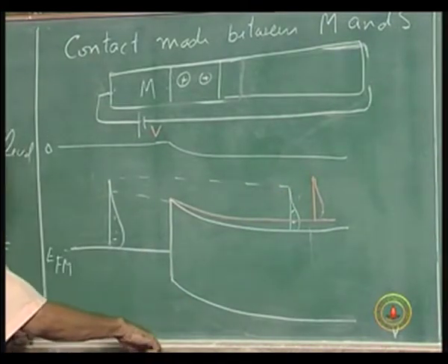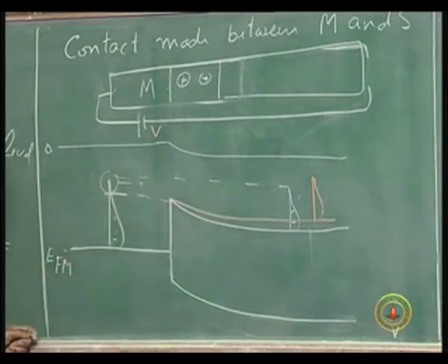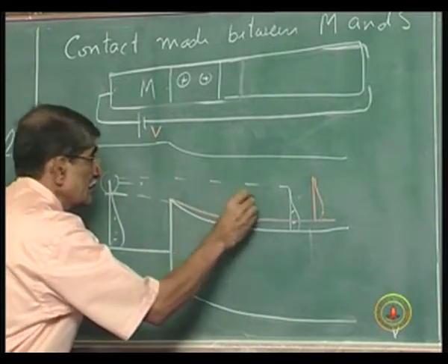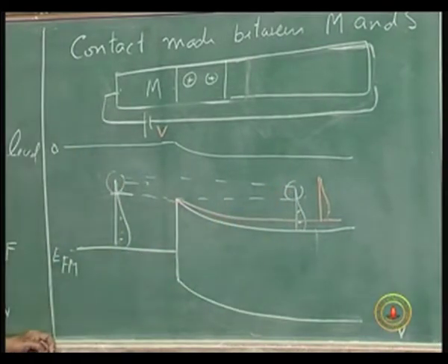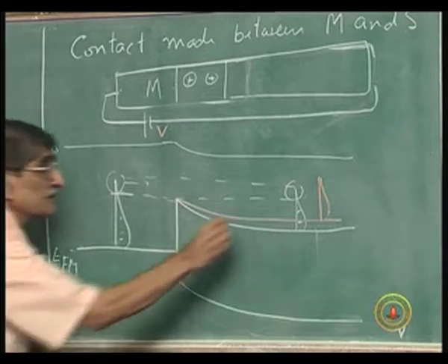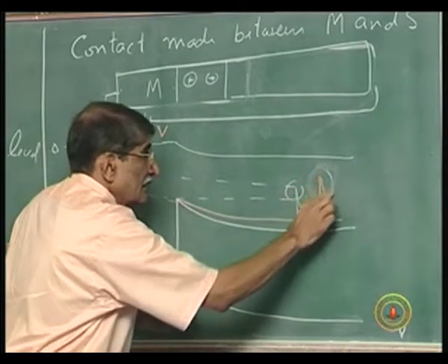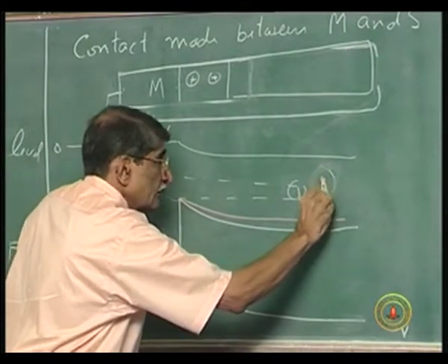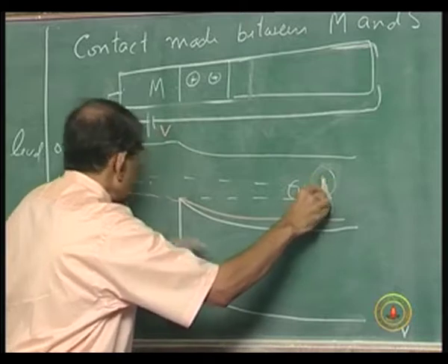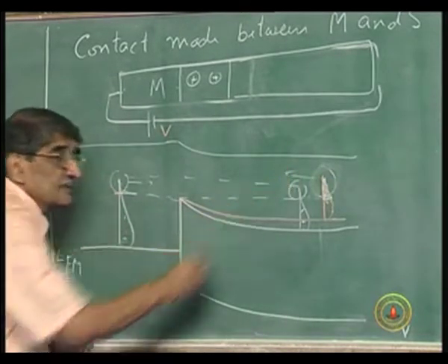Originally you had these electrons which are capable of crossing that side, and correspondingly these electrons which are capable of crossing. Now, you have these extra electrons. In fact, the integral from here to here gives more electrons than this number. So, this gives rise to extra current in that direction.